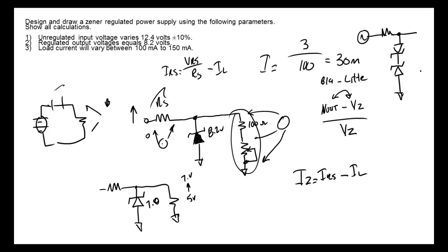So what would happen if this went too positive? This guy would act like a diode. This guy would, because it would be forward biased, right? You understand? And it would clip off the positive alternation. So here is one situation where we're using one just like a forward biased diode, and then of course on the negative, which one's protected? This guy's protected on the negative, right? You understand? This guy would be acting just like a diode because it would be forward biased.